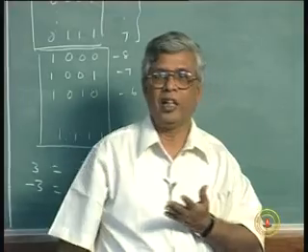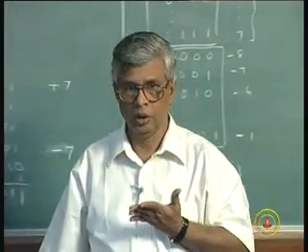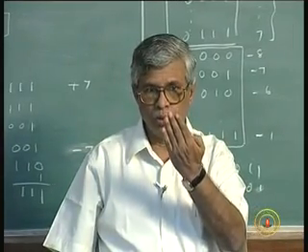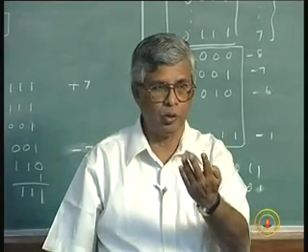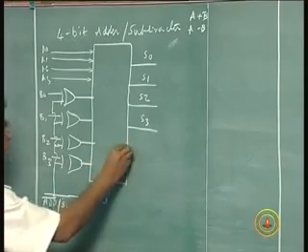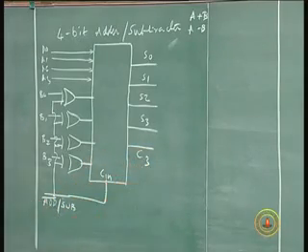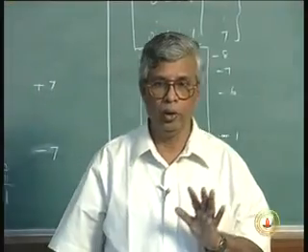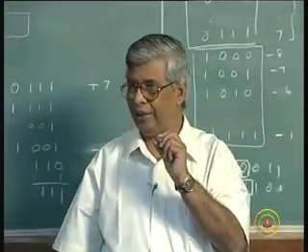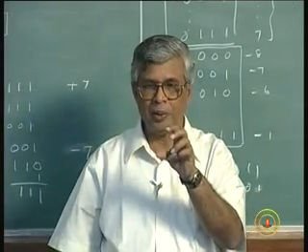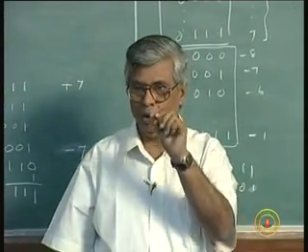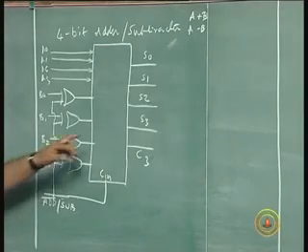Is carry significant or not now? Because the 4-bit adder will give you 4 sum bits S0, S1, S2, S3 and a carry bit, which we will call C3. But does C3 have any use? No, because we are only talking of 3 bits now. The 4th bit is a sign bit, and the result will always be a 3-bit magnitude and a sign bit, and the 4th bit S3 will be the sign bit,